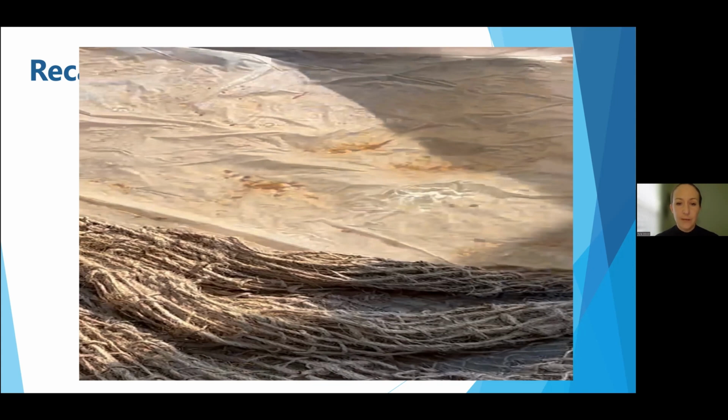And if you think of bacteria as the same concept, a kind of biocolloid, you can use polymers to both prevent microbes and bacteria from being washed out of soil when you're using it for erosion control, and you can also use it to remove bacteria. The only thing is there are rules for treating algae and treating bacteria, since the PAM is not registered for those uses specifically. So it's something to check on. But can it? Yes, it can.